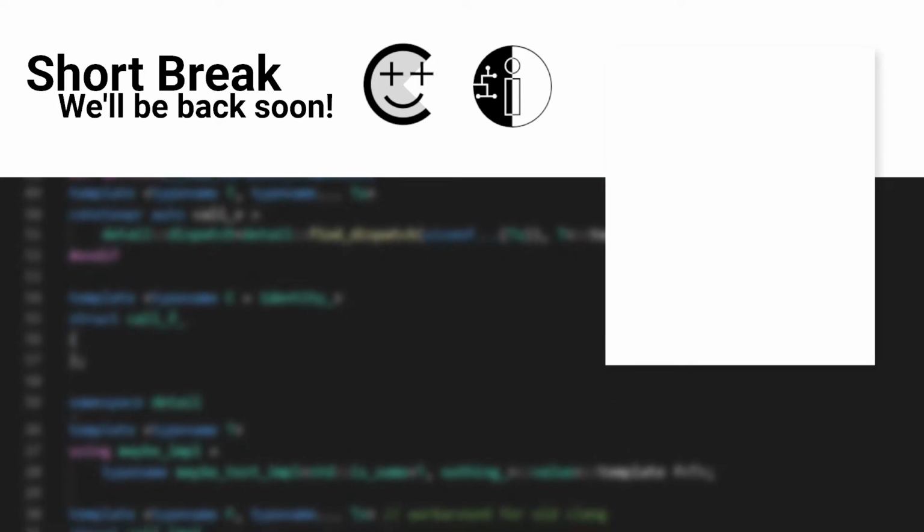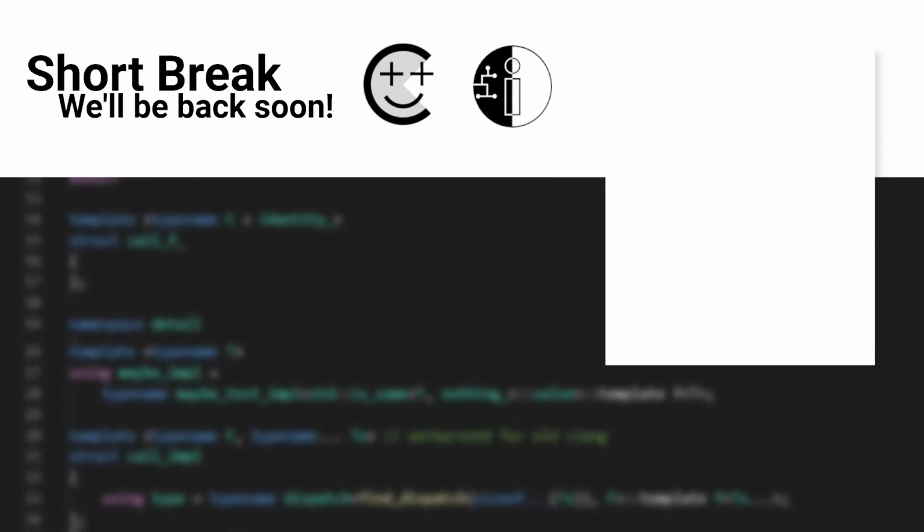But let's be honest, the tool of choice for you at home that just wants to have some fun is probably going to be a debugger. Because with the debugger, you can just, well, often connect to the device, use the debug interface, and extract the firmware that way. So you have the firmware in some way.